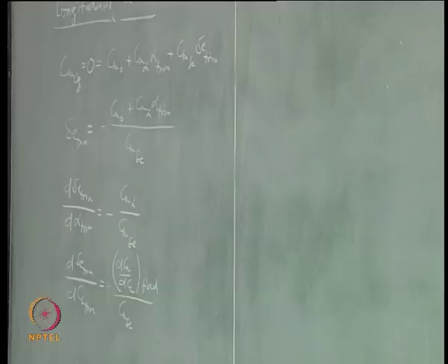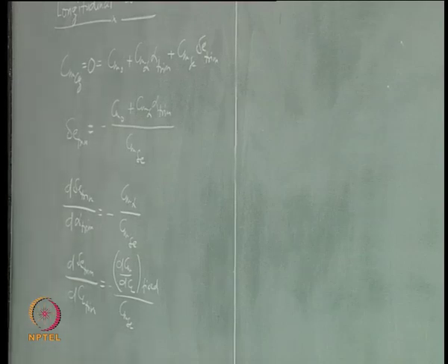So, clearly the amount of static margin that you have, or the pitch stability that you have, is also going to determine how much force a pilot is going to feel, right, when he is trying to change the elevator.